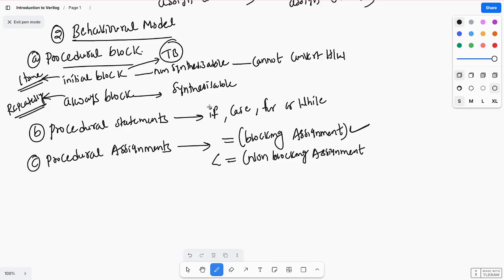When the tag is identified, the gate will open for one car, and after that the gate will close. Then the next tag is identified, the gate will open and one car will move. Is there any chance to overtake other cars? Cannot. You need to do it line by line. That is the example of a blocking assignment. Blocking assignment means one instruction is executing, and the next instructions will be in the blocked state. Do you understand?